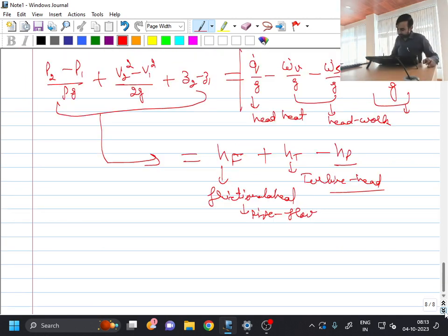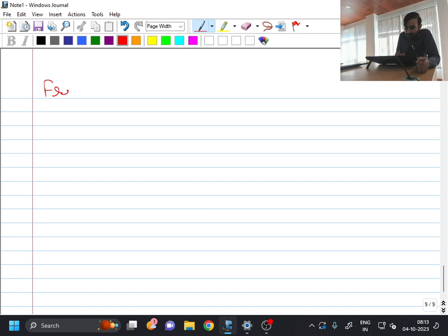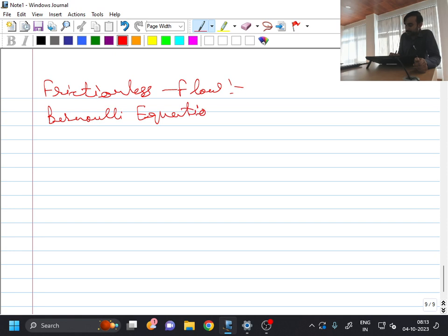Let's see next. So next is our frictionless flow. Why am I calling it frictionless flow? Because I will now be discussing the Bernoulli equation, and the key feature of the Bernoulli equation is that it is applicable for frictionless flow. So to analyze the Bernoulli equation, we will be considering that I have a stream tube. You must know now what a stream tube is: the collection of streamlines forming a tube surface is called a stream tube.